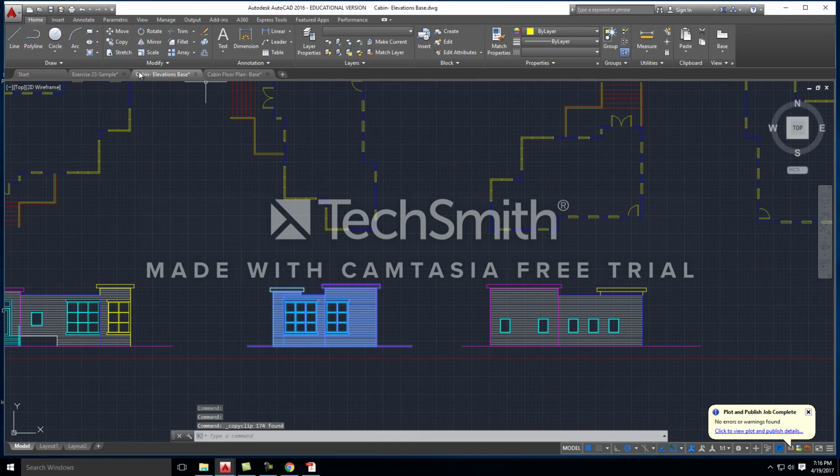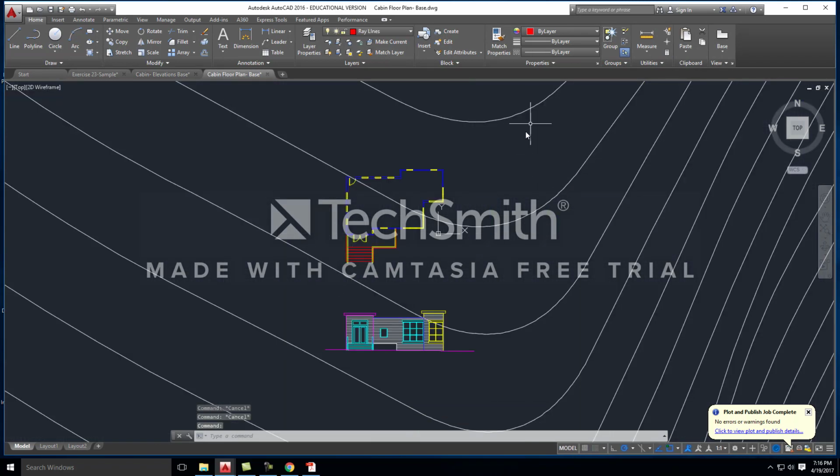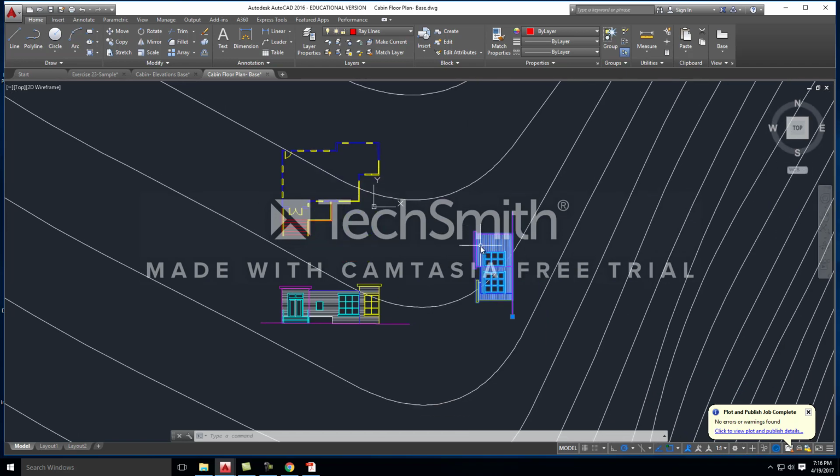I'm going to copy it. I'm going to bring it back over to my other floor plan. I'm going to paste this as a block. All right, and I'm going to rotate it 90 degrees like so. Now, some of you guys may have done this last class when we were working on creating our elevations: we actually extended our ray lines and we started drawing our elevations. It's actually a fairly common process to radiate them around the floor plan.